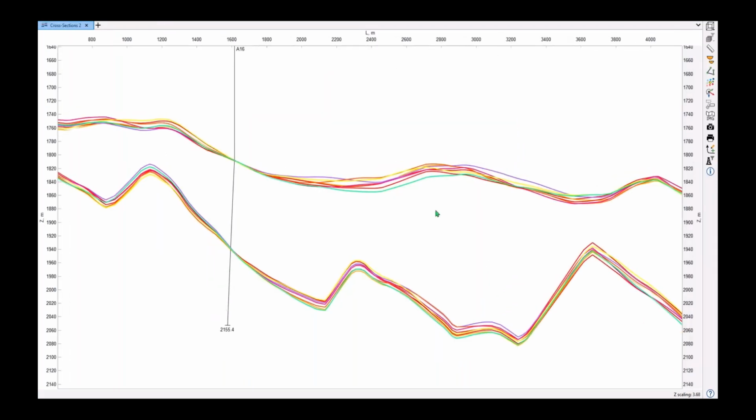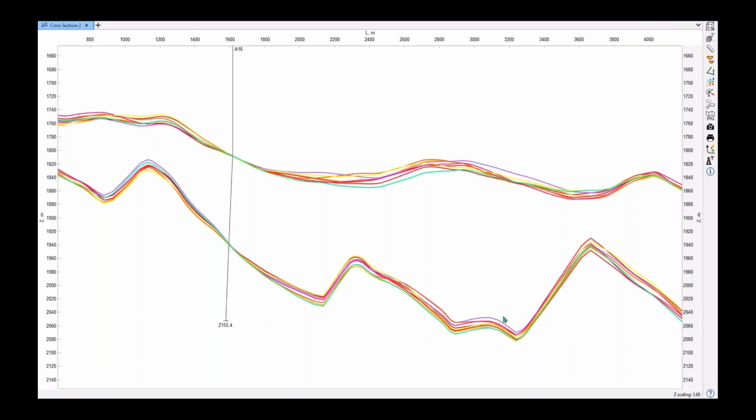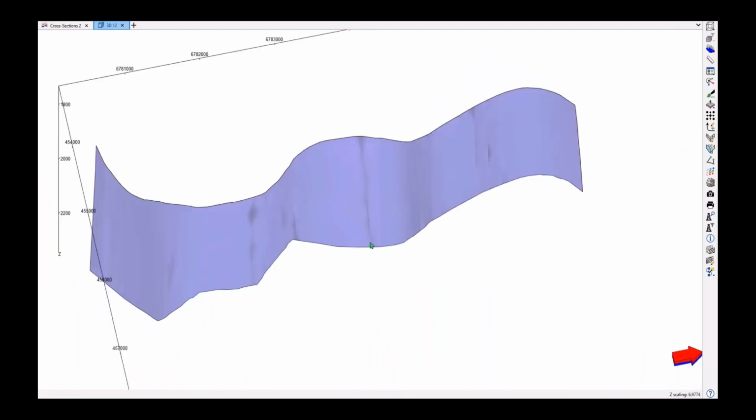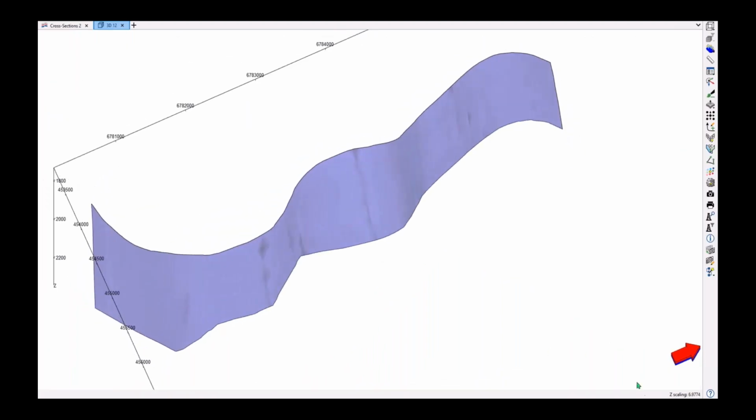Here we've created a multi-well fence attached to our markers, and we can see that the horizons that we've output come towards one another, towards our hard data points at our wells, but flex away by the given range that we've stated, from -2 to 2. You can also attach a scalar to this as a variable that allows you to flex it even further. As I mentioned, we've got horizons, but we can also do it for faults as well.